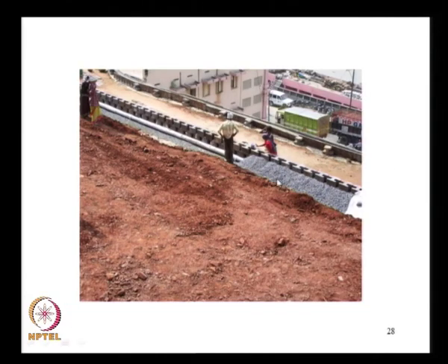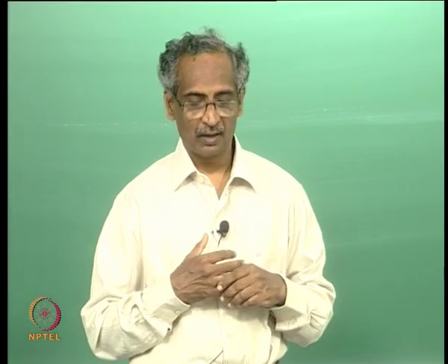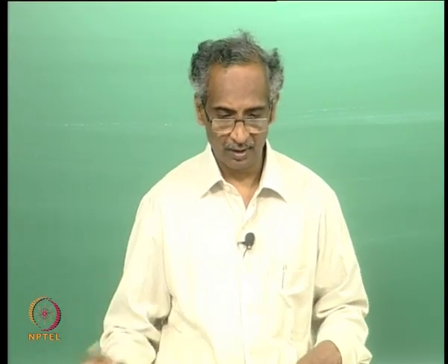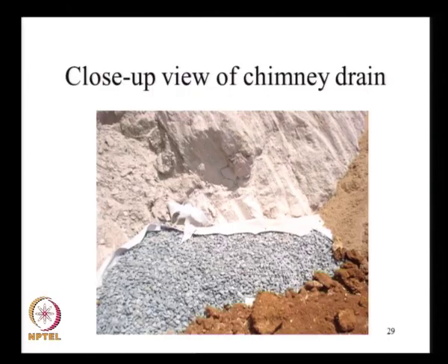And here you see another picture. Along the length of the wall, we provide another drainage pipe. Although we place the drainage aggregate, the purpose of this drainage pipe is to collect the runoff water and lead it safely away from the reinforced fill.